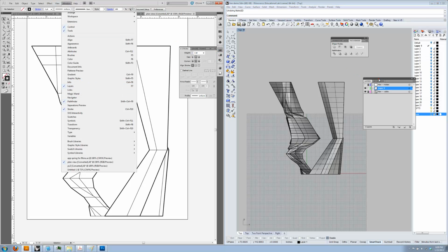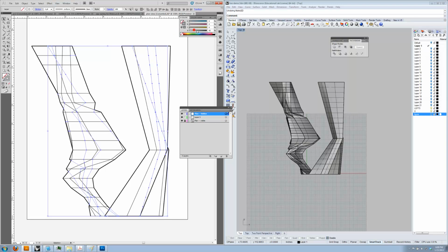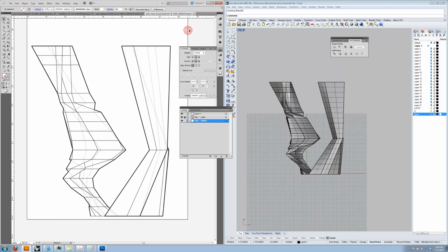Go into the layers menu, and now let's play with the hidden layer. I can click on the hidden lines, and I can do a couple things with them. I could start by making them gray lines. And note the layer order matters, so since they're hidden lines, they probably want to go underneath the other lines. And that may or may not have information that's helpful. So you could do like a fine gray line. So these are maybe 0.75, gray. And these might be 1 or 0.75 black. You have to adjust it for your taste and for clarity.